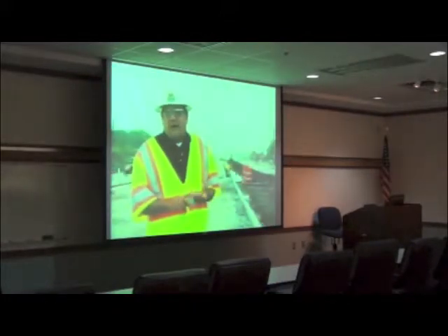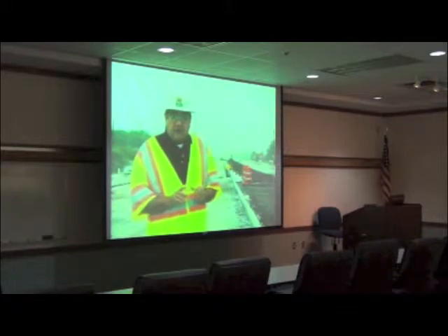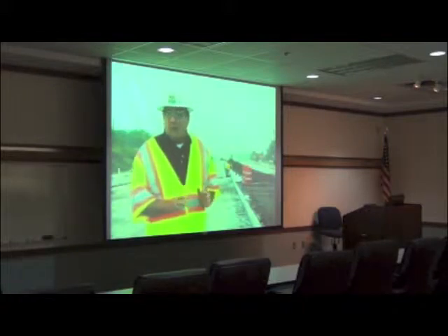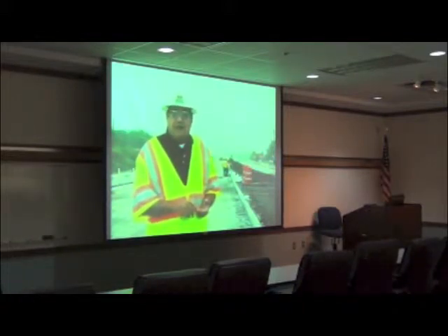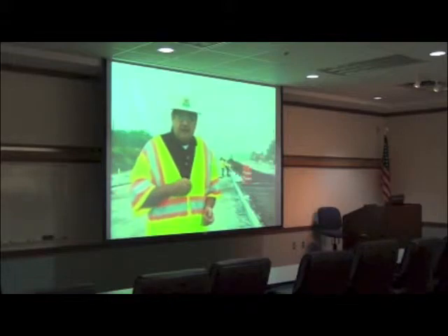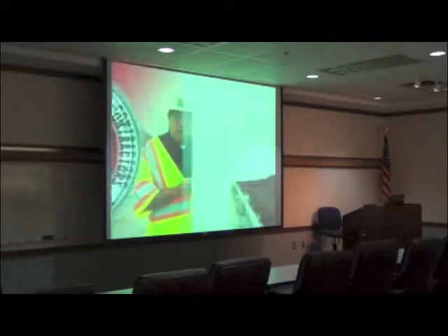Construction employees working on highway and/or road construction zones often risk being struck by traffic. Even the most attentive drivers and equipment operators may not see workers on foot, especially when light levels are low, at night, or during bad weather, for example. The best protection against these kinds of accidents is to wear high visibility clothing.